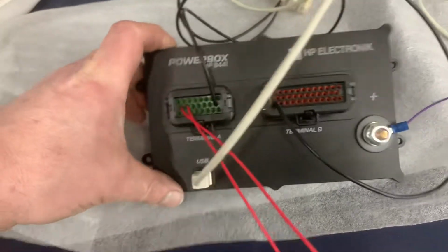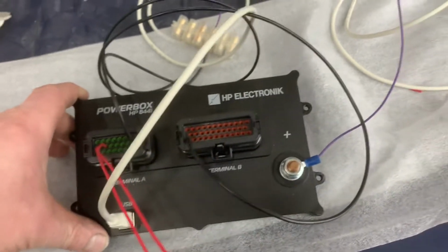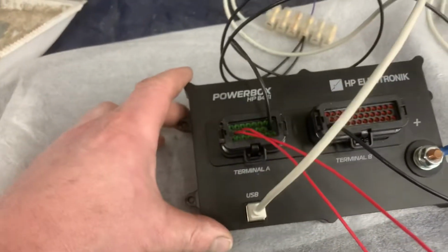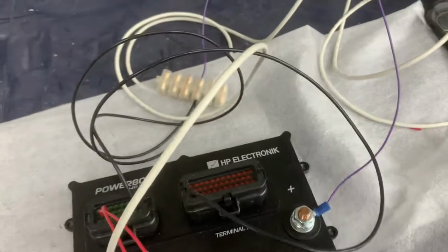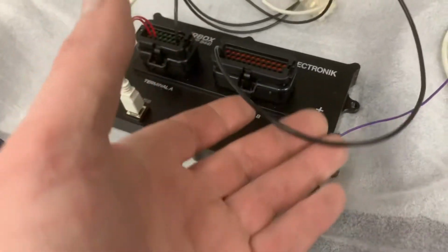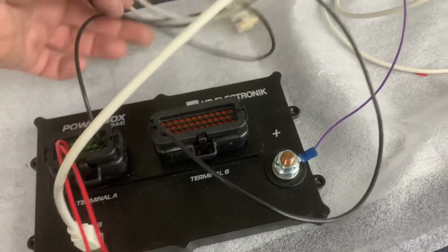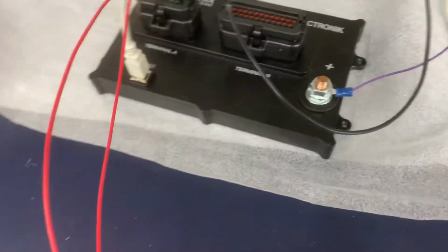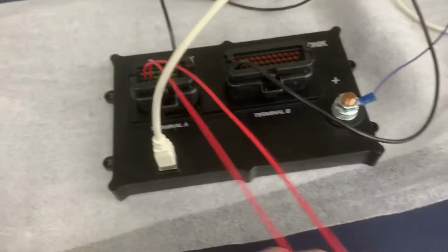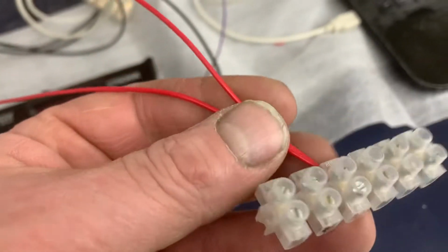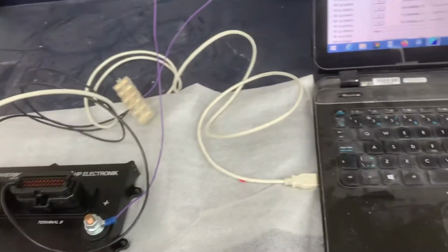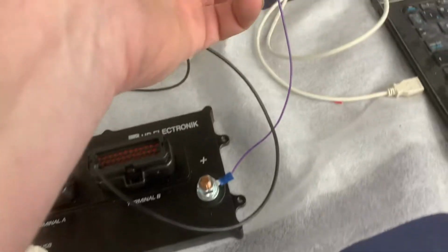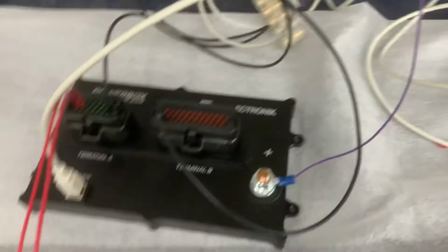So the HP Electronic PDM, I just wanted to test that the ones we bought were okay, and just did a quick mash up to make sure everything was good. So I had to ground two connections, one on either plug, and there is a 1/2 amp supply from the unit with an ignition return. So simple enough. Basically now this thing thinks it's plugged into the car. Yes, okay, that's not a 200 amp supply, but we're not really switching anything at the moment.